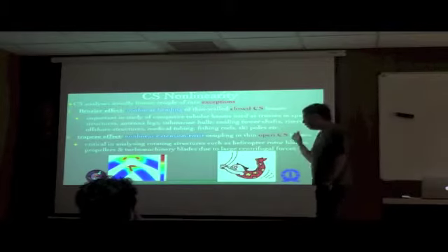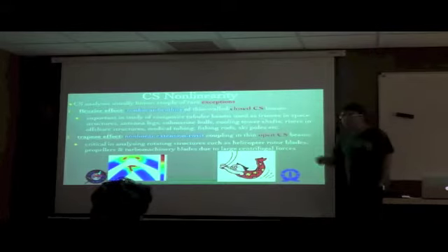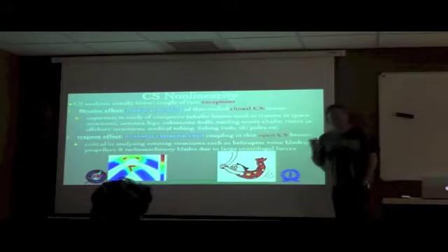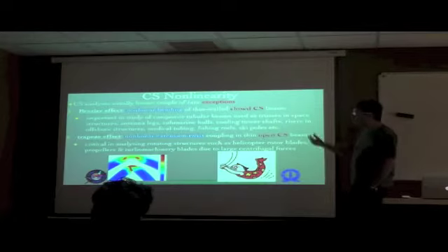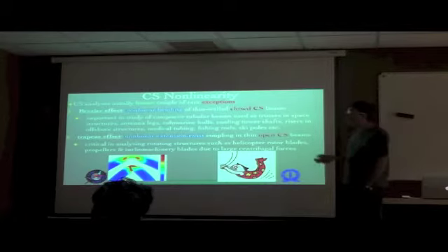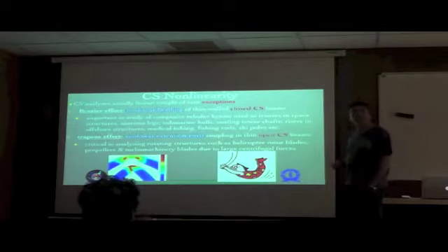Then you have propellers, again because of the same reason, that they are rotating structures and therefore centrifugal forces are in place, and centrifugal forces are tensile as far as the beam is concerned. So that automatically comes into picture. Again, because of the aerodynamic loads and or certain control loads, you will have torsion coming in as well.